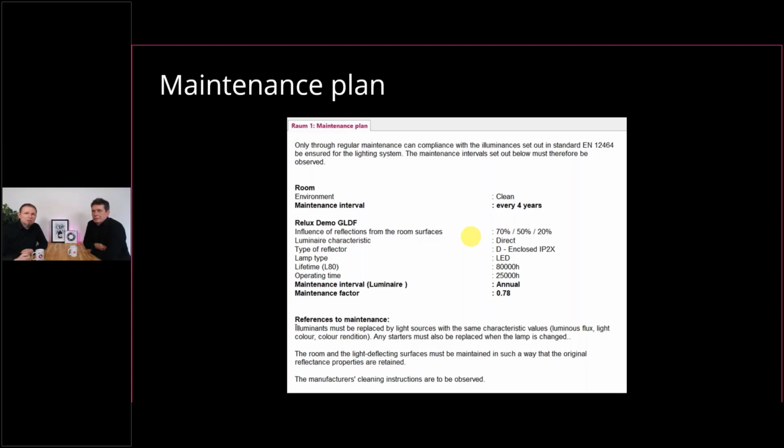You need to have more light power in order to deal with this maintenance gap. So this is really serious, that you communicate at least, maybe by providing the results and saying: I did not get any maintenance information from you, I need to do estimations, I need to guess something, and this is my guess. Maybe you get something sent back, like: oh, we maintain quite often. If you have serious maintenance in the building, you can have fewer luminaires in it. This is really the case. So if you have good maintenance, if you clean the environment, then you need less energy, fewer luminaires, and have a better design.